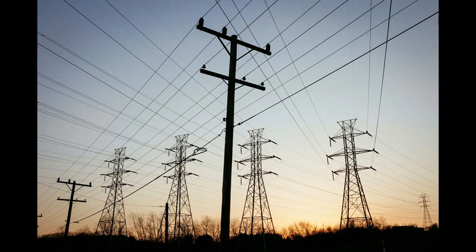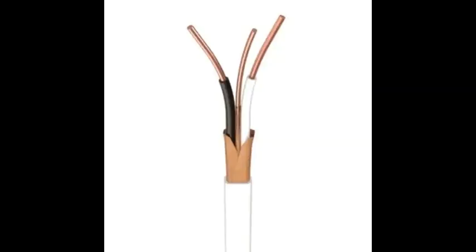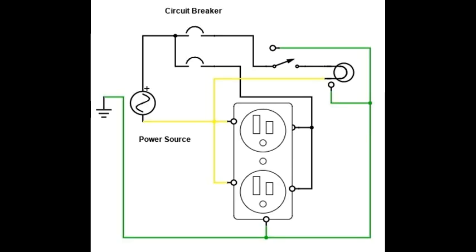It is the primary way that electricity is delivered to homes and businesses and is used to power many household appliances. In a basic AC circuit, you'll have 3 wires. And again, everything I'm talking about is US only. I'm not familiar with the standards in the rest of the world. But in the US, a black wire is the hot wire, a white wire for neutral, and a green or bare copper wire for ground.